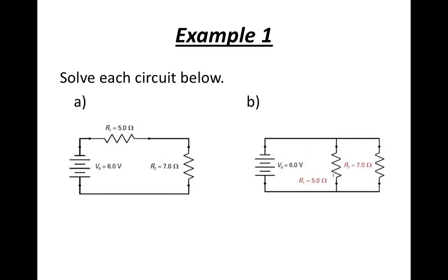So at the end of every circuit analysis problem, you want to check within your table that every row satisfies Ohm's law, and you want to look, based on circuit connections, that KVL and KCL are satisfied, because you don't necessarily have to use Ohm's law for each row. The good news about these problems is there always is a way to check.